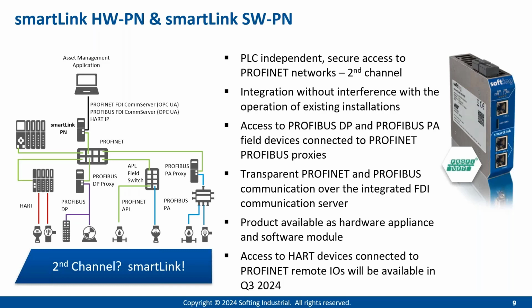And we will add in Q3 also support for HART devices, which are connected to remote IOs here on the Profinet network. In that case, we will use, again, HART IP for the communication from asset management to the HART devices you see here.